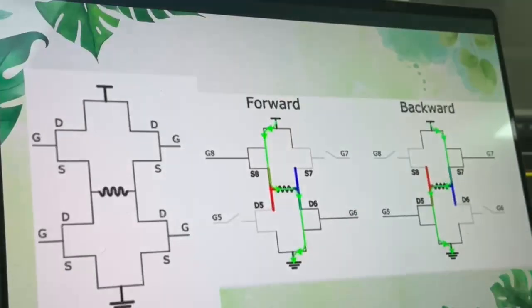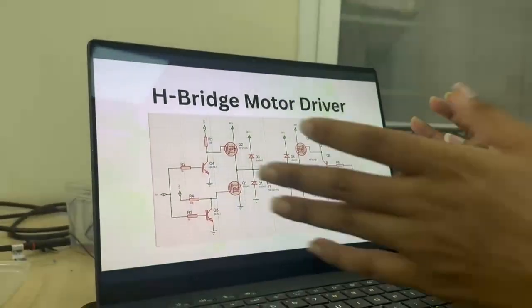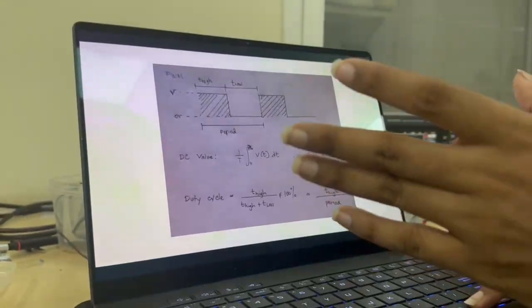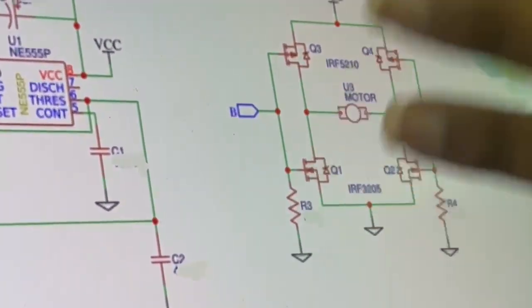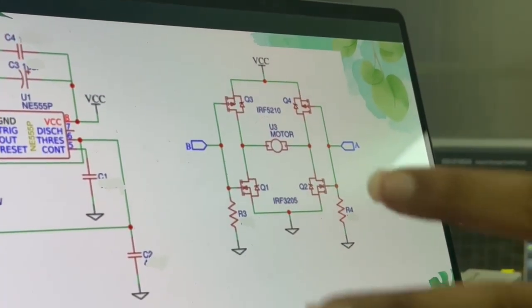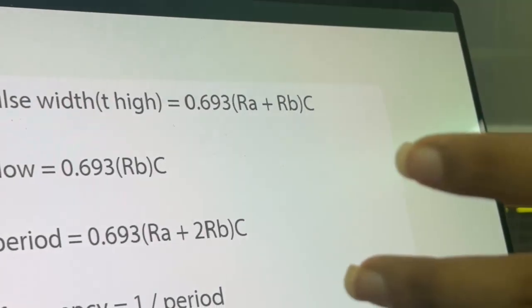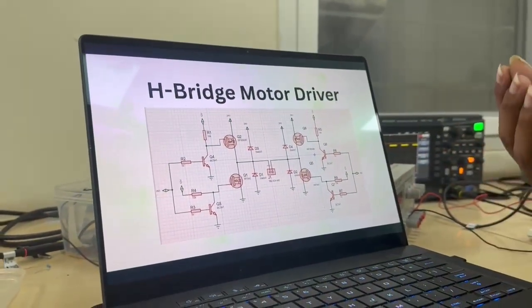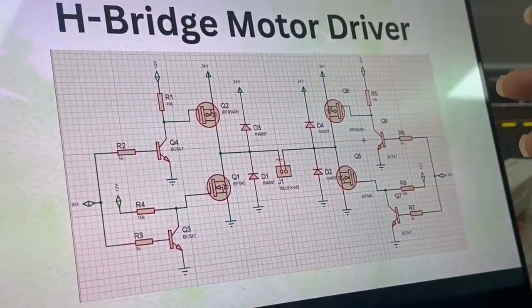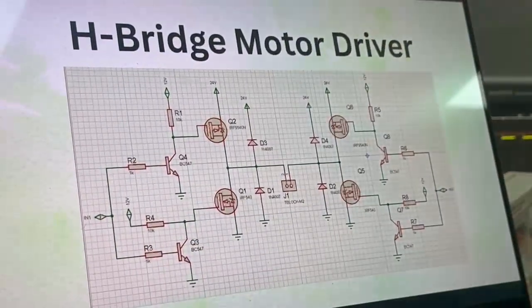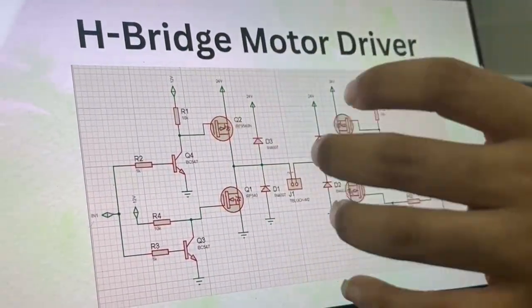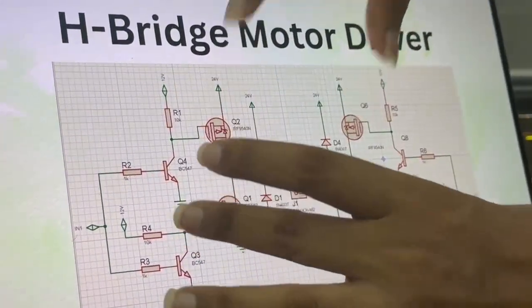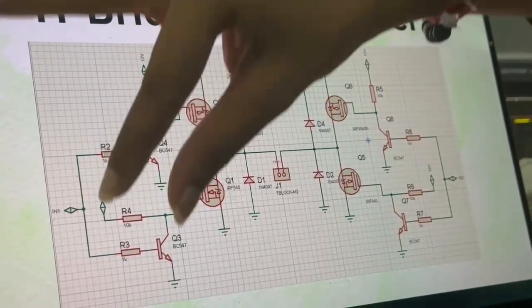And how was the H bridge working? Initially we had a circuit similar to this. This was then changed because of some issues. Irrespective of having the gate driver, we were getting very small voltage inputs through A and B. Thus, before the H bridges, we added amplifiers over here.